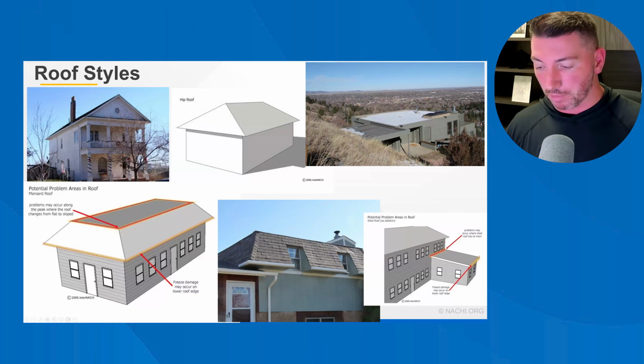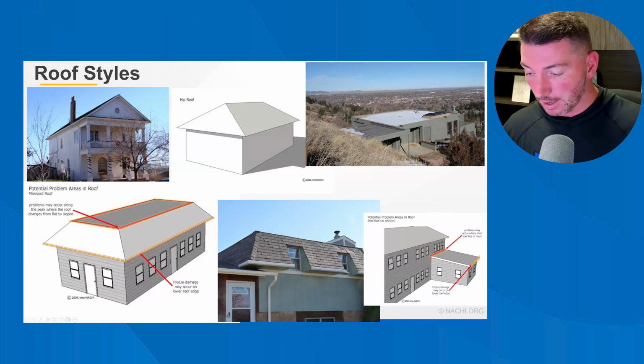When you inspect a home with a butterfly roof, look closely at the ceiling and floor beneath that low point, because for obvious reasons, a lot of water is going to pool up in that middle. The house in this photograph had recently sold, and the sellers had hired a contractor to install a new roof. The buyers moved in, it rained, and the roof leaked. The buyers had to hire both a different roofing contractor and a floor contractor.